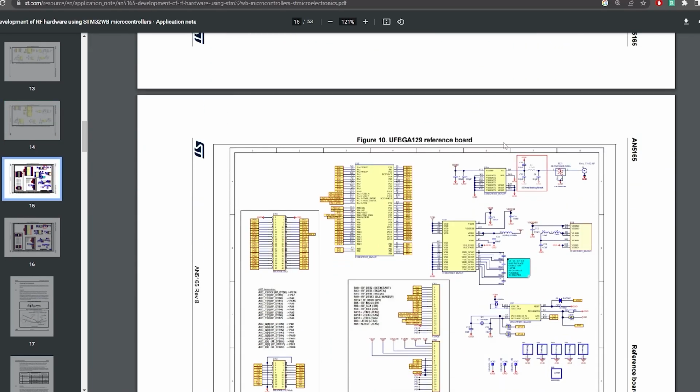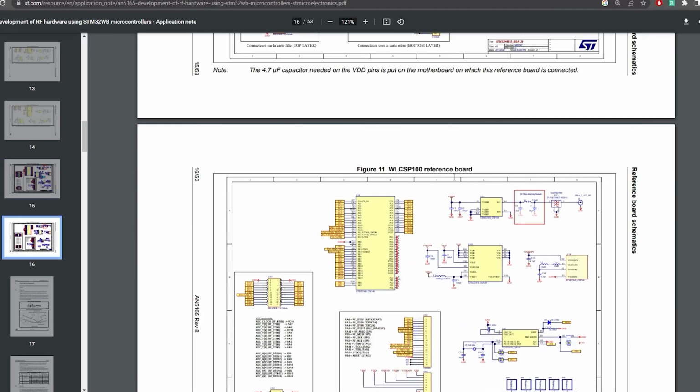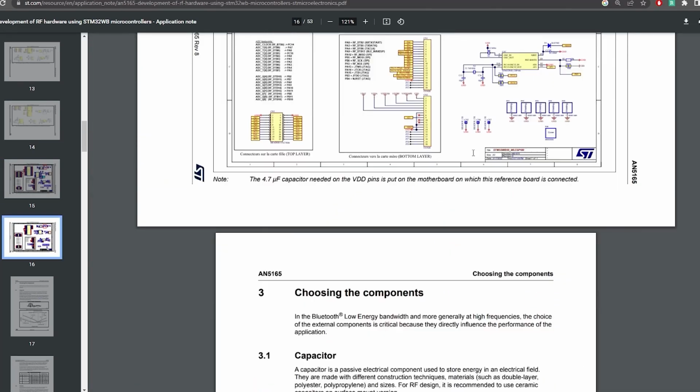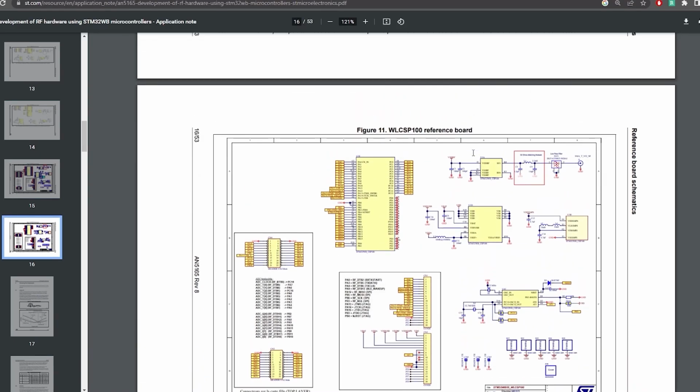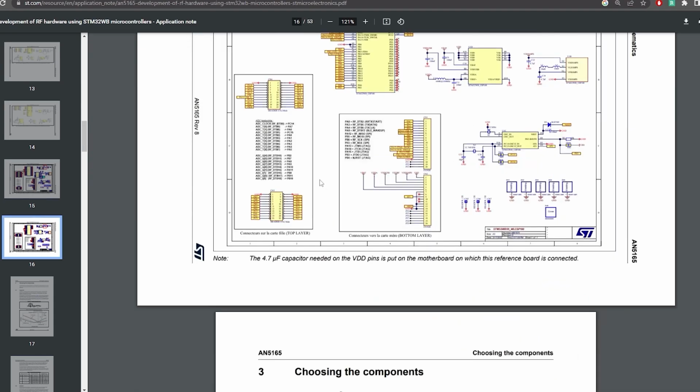Again, I've asked many others what they think about taking reference schematics, especially with RF, as it's a totally different world. And what I've been doing, and what others have said they do, is use the reference schematic to get them up and running, until certain values need to be tweaked, until they're looking for something specific. But if it's something to get up and running, the reference schematic is the way to go, and you don't have all this headache.